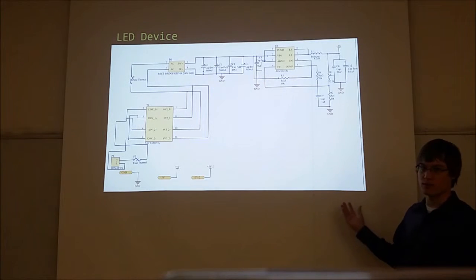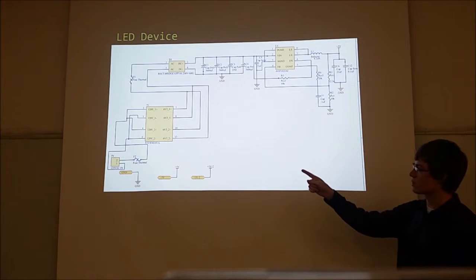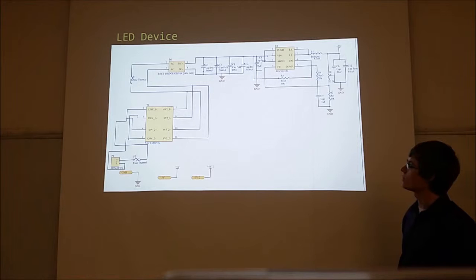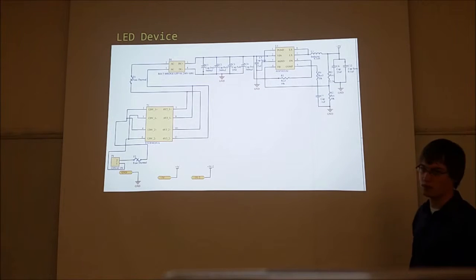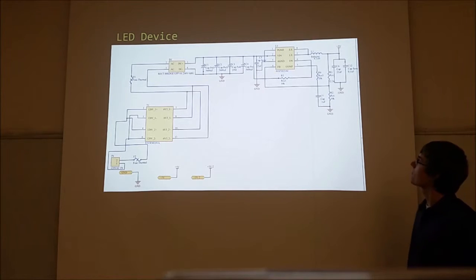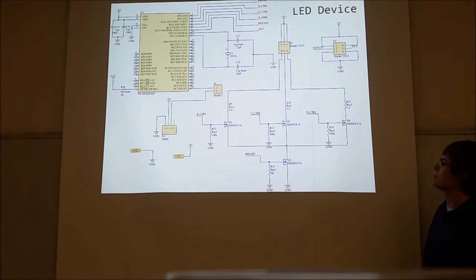This is the schematic for the part of the device, which has the transformer coming in, transforming it to a 6.3 volt rectifier bridge, labeled D1 over there, 3 bank capacitors for containing the ripple, and then we've got over here the regulator circuit. This is the microcontroller and Zigbee, as well as all the LED controls in this schematic.